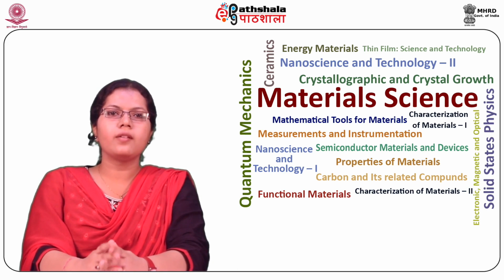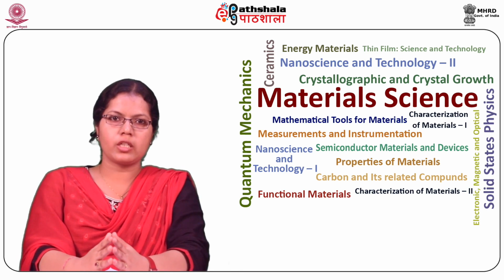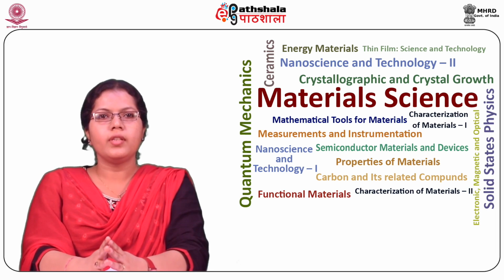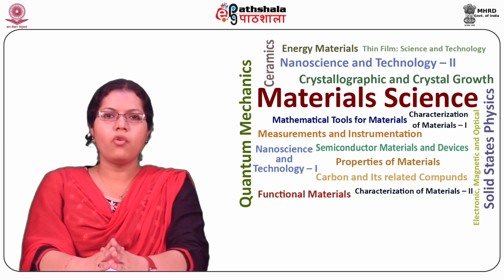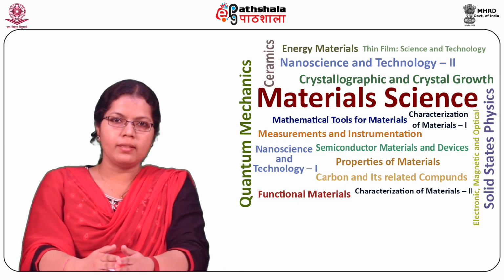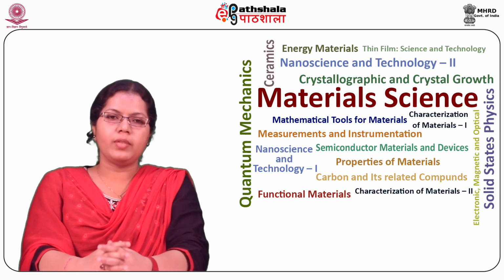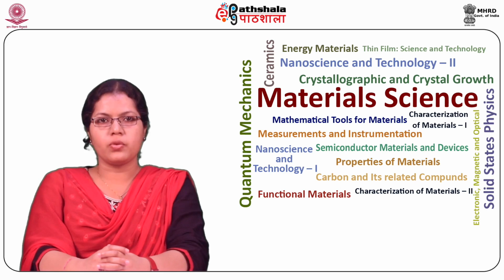Third is the photovoltaic transducers. These are based on the property of photoelectricity generation. Devices such as the photodiode in combination with the diaphragm are based on this property for their application in the measurement of pressure. Next is the electromagnetic transducers. These are based on the property of electricity generation by moving a coil in the magnetic field. Devices such as electromagnetic pickup are based on this property for their application in the measurement of flow. Last type of transducers are the galvanic transducers.